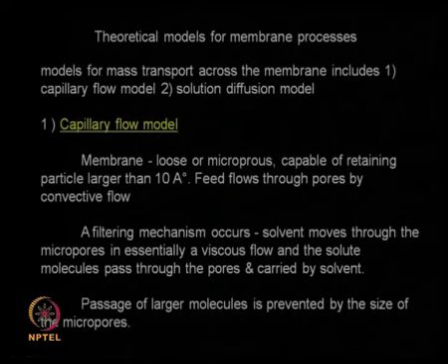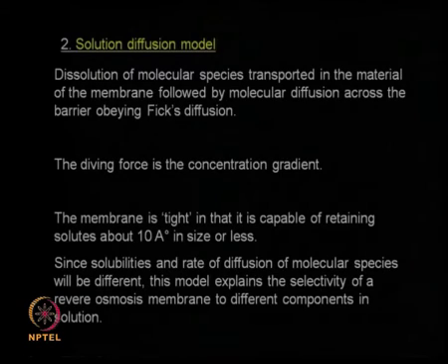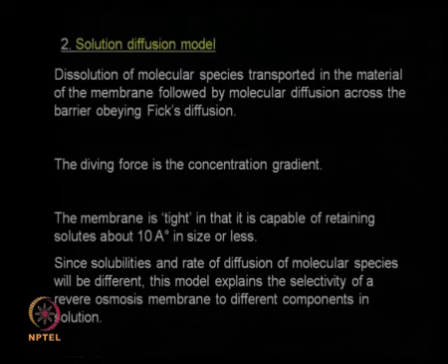The next model is called the solution diffusion model. Here the molecules dissolve and transportation through the membrane is by molecular diffusion, obeying Fick's law of diffusion. So here the driving force is the concentration. In this model it is assumed that the membrane is thick or tight or non-porous, there are no pores here.